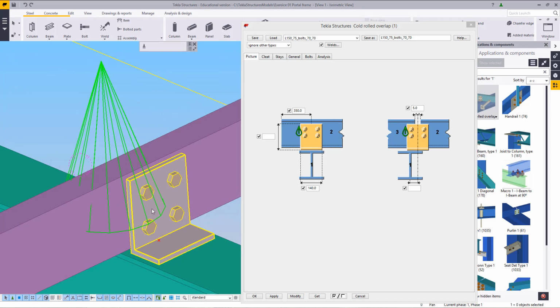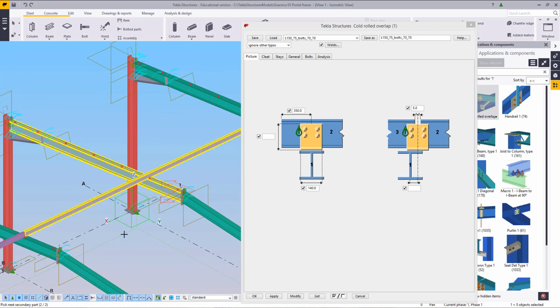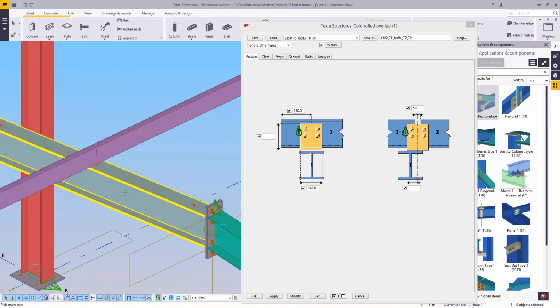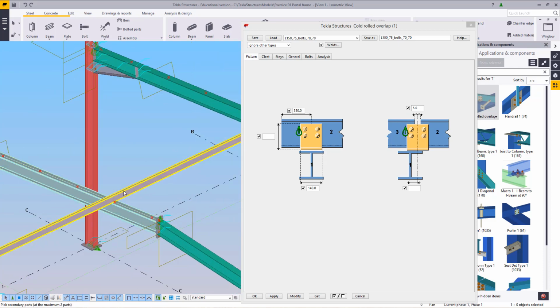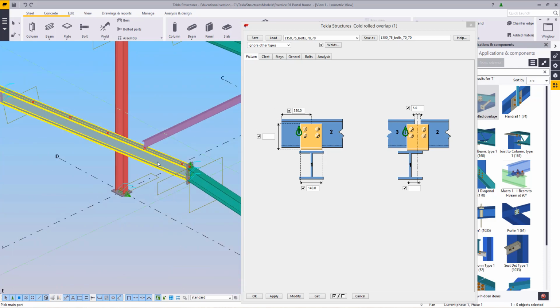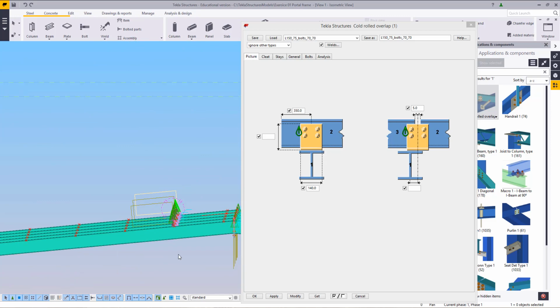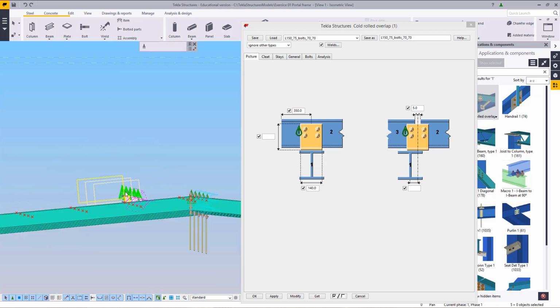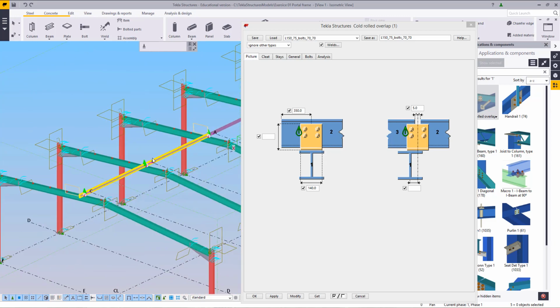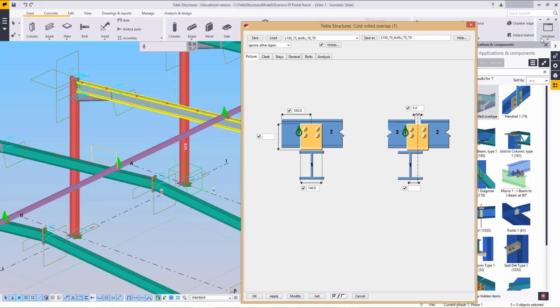As you can see, we've got our 2 bolts set at that distance, and I'm going to just select those 2. Here I would like to select both sides before confirming with middle mouse button. These ones are just the 2 items and confirm, 2 items and confirm. Afterwards, I'm going to get a nice little side view, select all of my components so that when I press modify, all of them will modify at the same time.